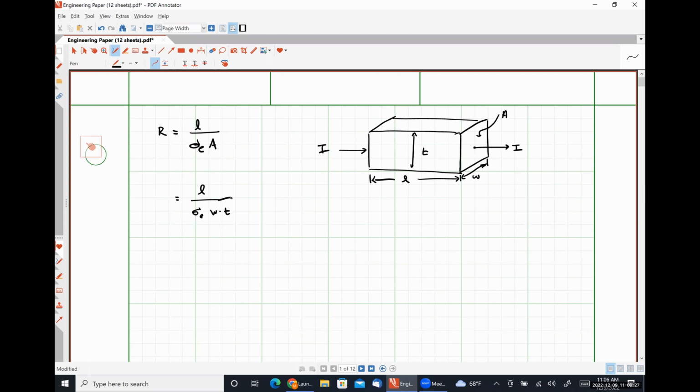So the implantation depth or the depth of diffusion will define the resistance that we get. Everything will be of a particular uniform thickness. So instead of dealing with absolute resistances, we largely deal with what are called sheet resistances in MEMS devices.